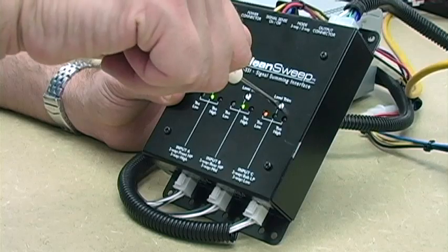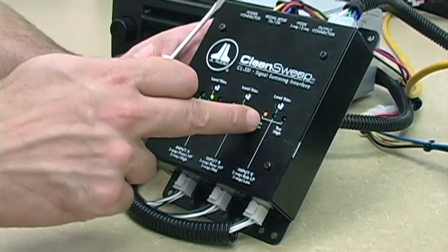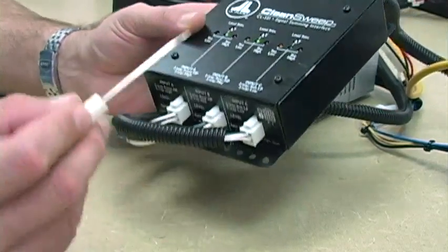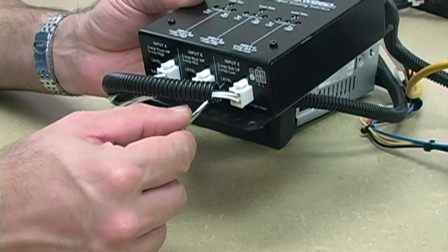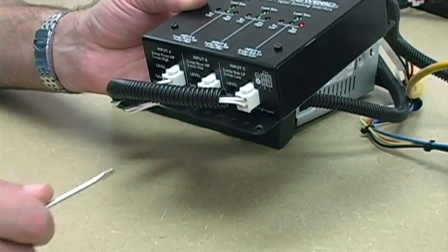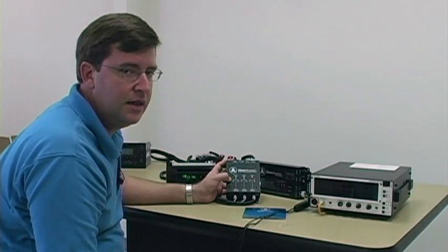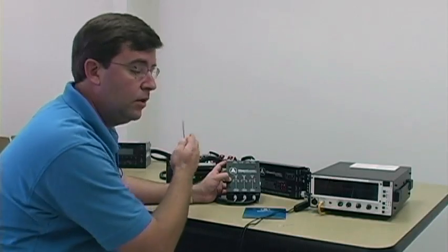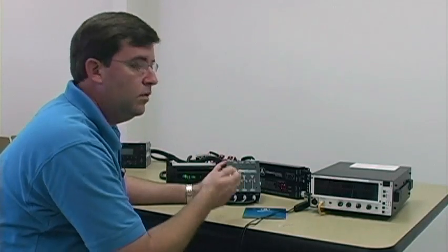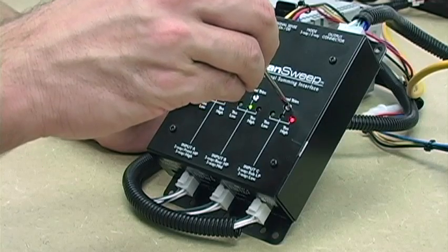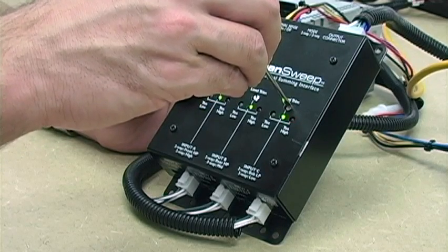Okay, Houston, we have a problem. I turned it all the way up and it's still telling me it's too low. The unit's essentially telling you at that point that isn't a speaker level signal, and you need to go over here and flip this switch over to line level. Okay, so even without really knowing that that was a line level output out of the radio, the unit will tell you. Okay, now we've got a red light. That's too high. So we'll trim that back down. Hopefully get green happening here.